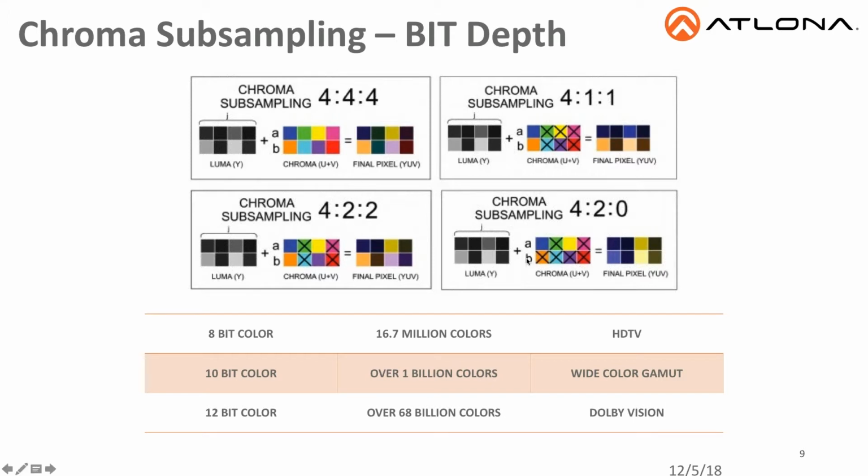And further still, if we continue to compress that pixel color, each one again is receiving its own luminance information, but only 2 pixels in row A are receiving their own chrominance and none in row B. So they are all sharing the same chrominance information, compressing that color information. So if you have any questions on that, we can go over that later also.